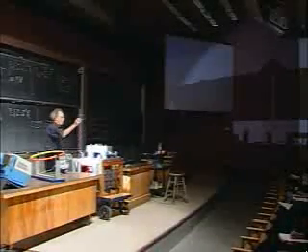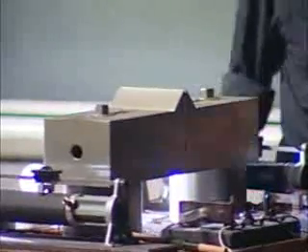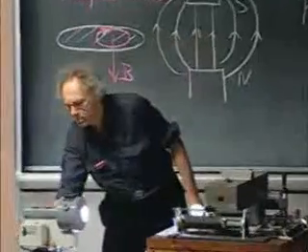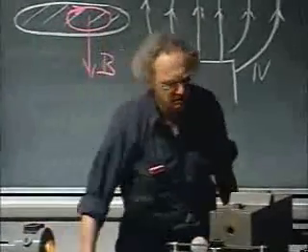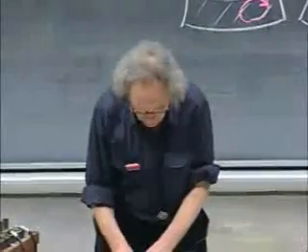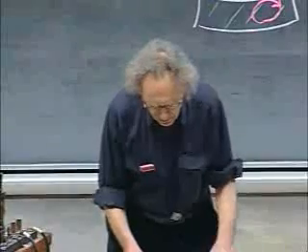Now, the one with the slot. Amazing, eh? Now, once more, the one without the slot. Magnetic damping. All of that is the result of eddy currents, all of that the result of Faraday's law. Heat is produced at the expense of kinetic energy.